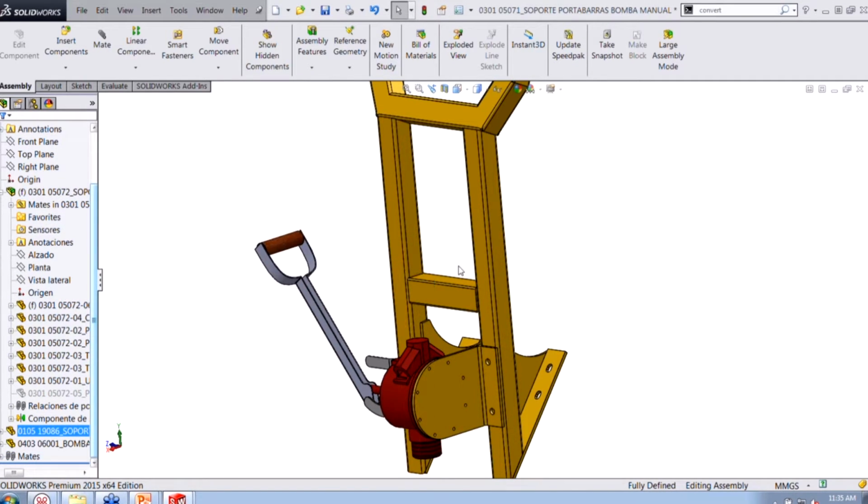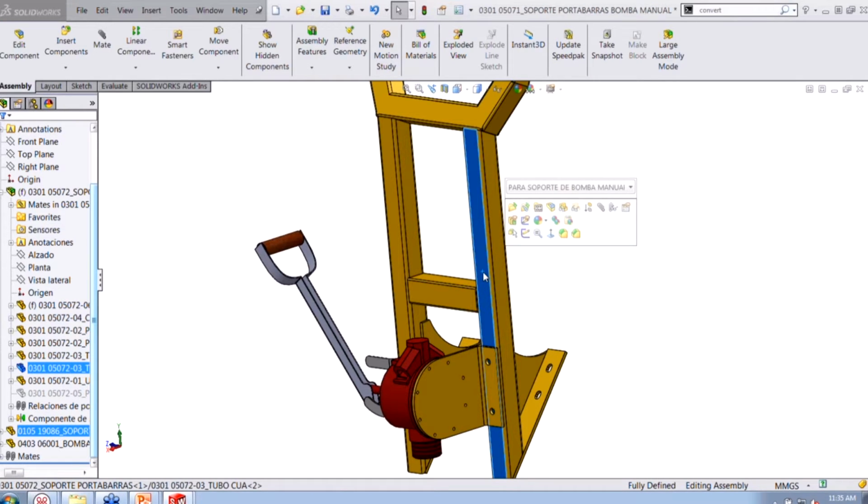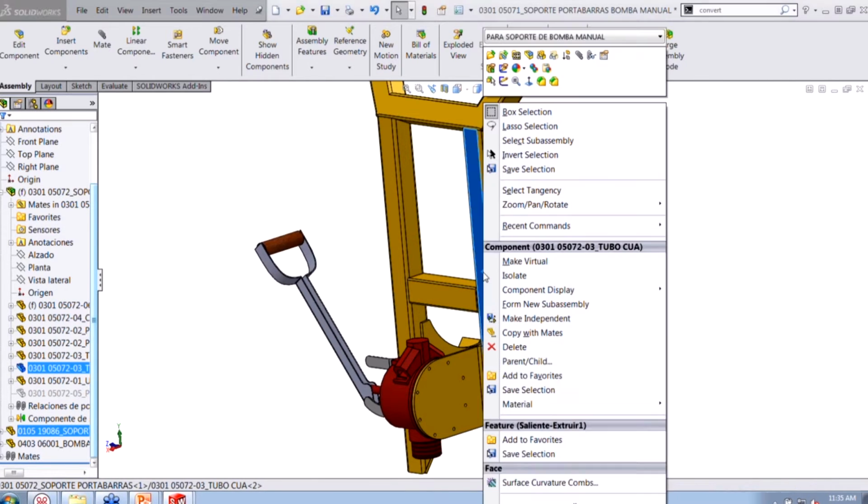And then now I'm going to make an in context edit. Okay, so I'm going to go and edit this part. It's almost the exact same thing as we've done before, where it has an external reference, how we did it with the pump card, how I was referencing other things, right? But you can also do this for real components too. It's not specific to just virtual. So here it's a real one. I'm going to right click and go to edit part.